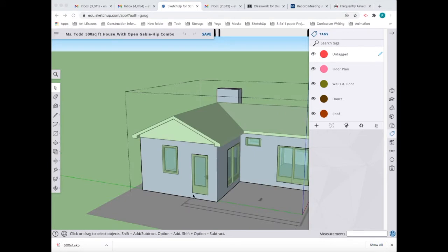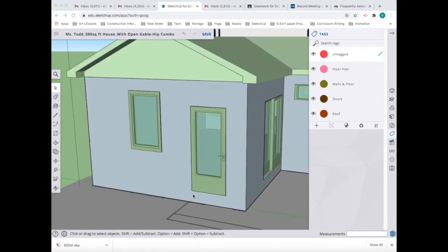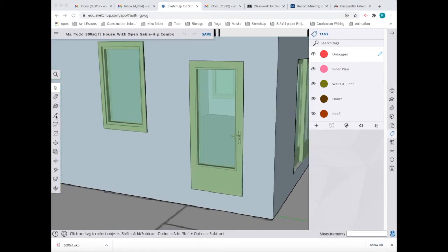So to start my step, I'm going to zoom in and I'm going to use my pencil tool. I'm going to establish kind of where I'm going to bring my line up. And I think I might have my landing start here. So I'm going to go on the edge point. I'm going to click up and sort of mouse over to the corner here and pull away. I don't know if you can see that that's a dotted line, so I know I'm at the right height. So I'm going to click here.